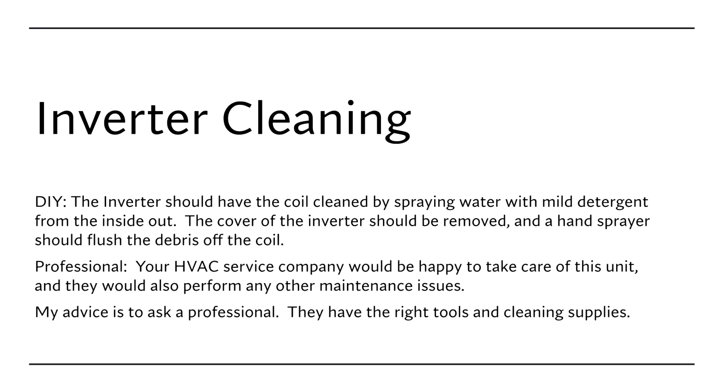All right. The inverter cleaning. You should clean this by using, again, mild detergent from the inside out. So you're going to have to take the, well, I don't want to say this. You have to take the cover off the fan, and you're going to have to spray the coil from the inside of the unit and push all the debris outside. So basically off the coil fins that are outdoors.